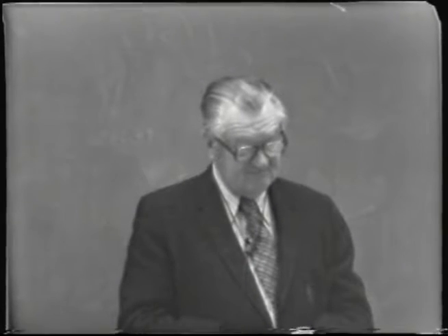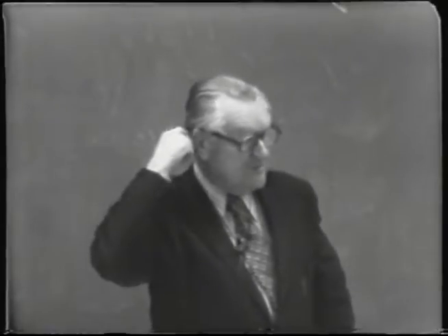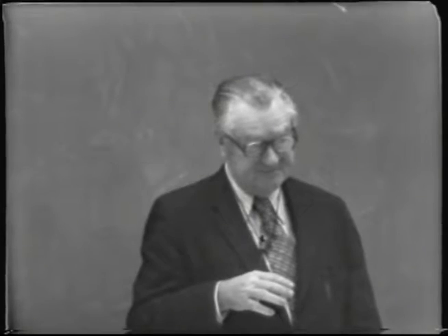And so, I'm sure if samples were taken on the trays below the draw-off, which probably, the draw-off of the side stream product was somewhere around 20 or maybe in the middle somewhere, which is all right. It's not a bad way to operate once you've got 40 trays there. But if you had taken samples of those trays immediately above the feed, you would have found them very low in alcohol, much lower than 10% alcohol, the composition of the wine, 11% alcohol.